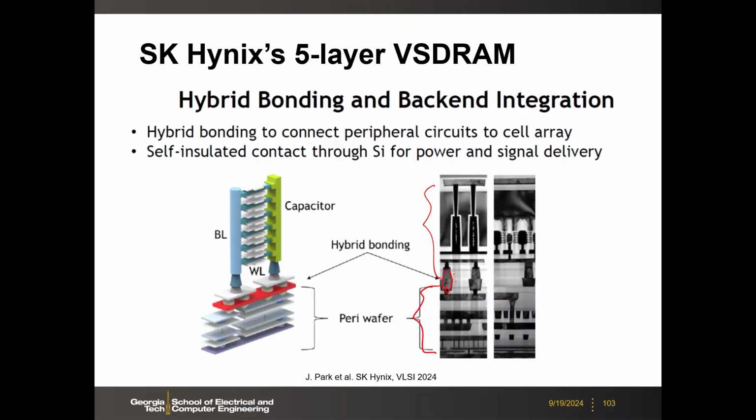That's 3D DRAM, like HBM. It's not true 3D. Those are pseudo or fake 3D. Those are made by bonding, okay? So here we are talking about monolithic 3D. You stack, or sequentially fabricate, the DRAM layer by layer on a single die, not by bonding. Of course, here we can bond the peripheral circuits, but the DRAM cell array is monolithically stacked in 3D. So this will be a revolution for the DRAM industry. Okay, so any questions?